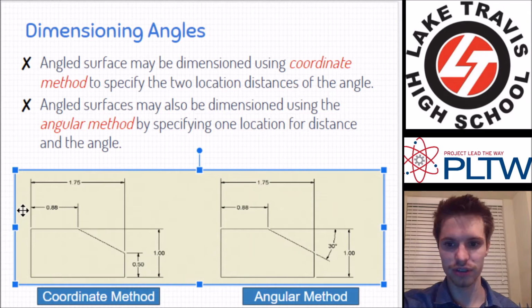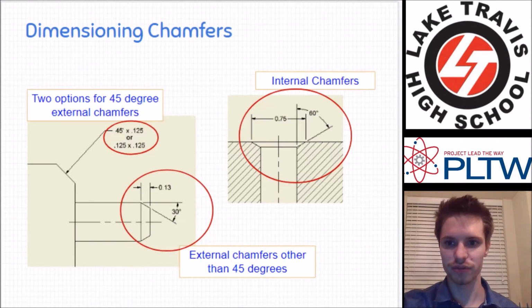You can find both of those points, and then this angle is just inferred, if you know both of those points. It's the line that connects them. Over here, you don't have this point exactly identified, but you do have the angle of this chamfer going on here. That's the 2 different methods there.